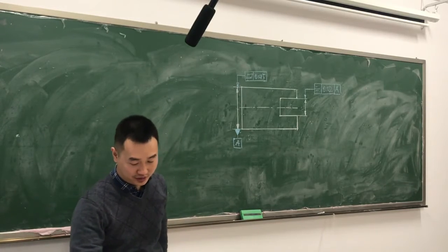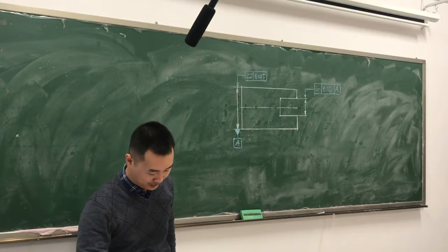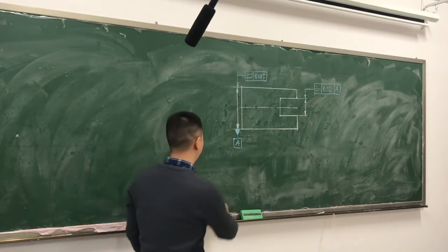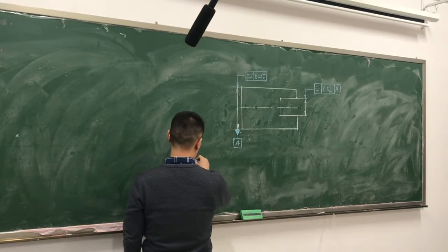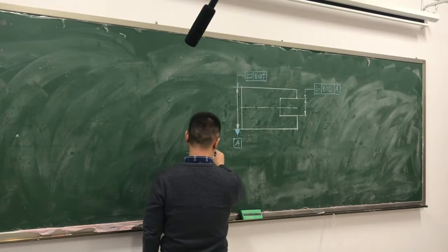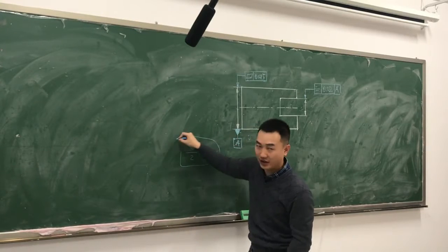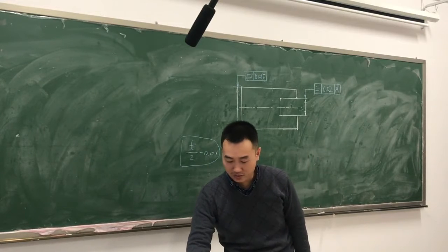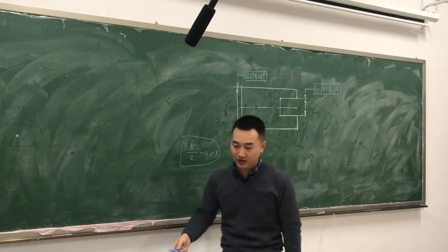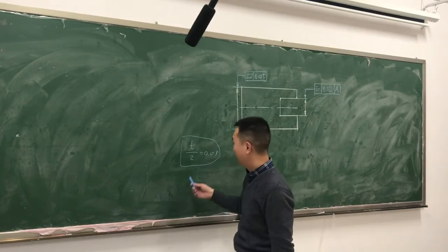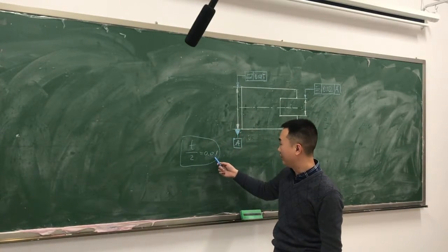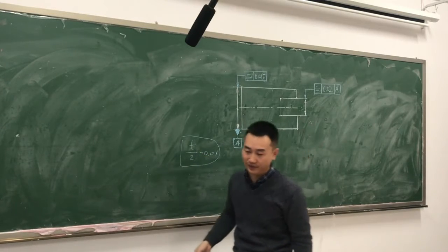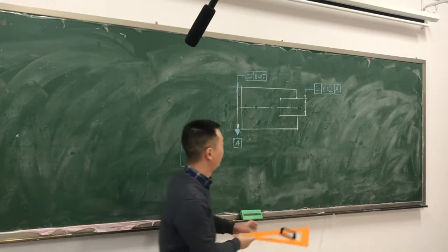According to the statement, the datum is fixed, and the given value here is t divided by 2 equals 0.01. If you understand, you should look into your book, and you will find that according to the statement, the 0.01 in fact equals half of the tolerance value, okay? And then you should label it like this.